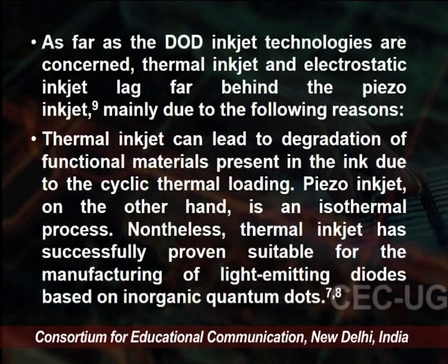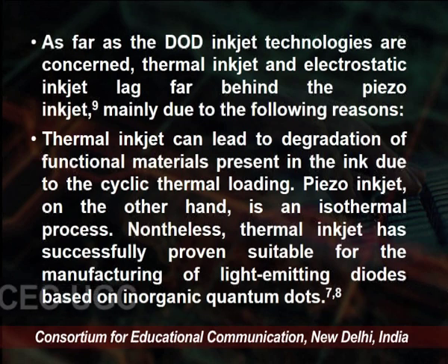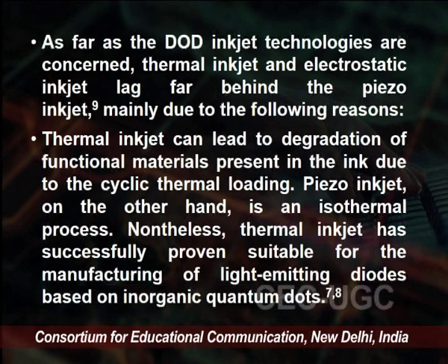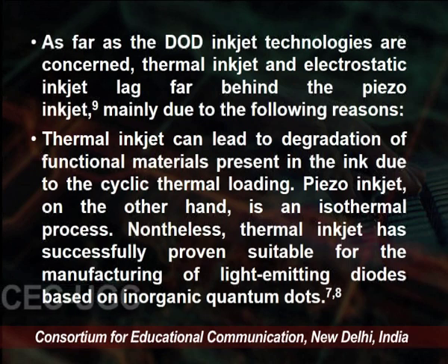Thermal inkjet has successfully proven suitable for the manufacturing of light emitting diodes based upon inorganic quantum dots. The range of ink solvents that could be used in the piezo inkjet is much broader than that of the thermal and electrostatic inkjet.